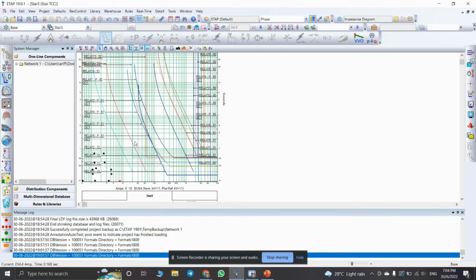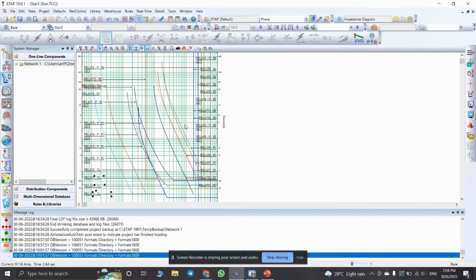Basically, the long time trip value will respond to overcurrent, while the short time trip and instantaneous trip will respond to short circuit. In addition, all the relays' characteristics are shown in standard inverse characteristic. So it is called an IDMT relay, in which the operating time is approximately inversely proportional to the fault current. I think that is it for part E.